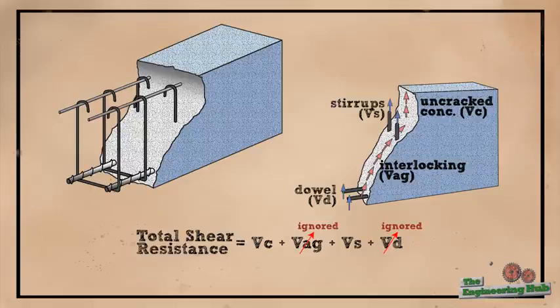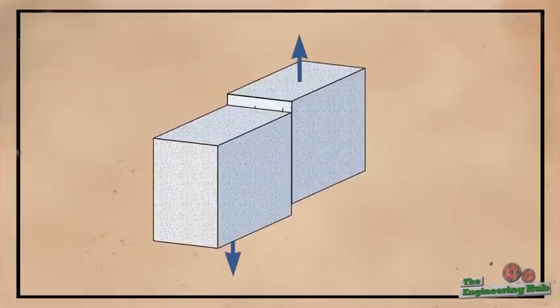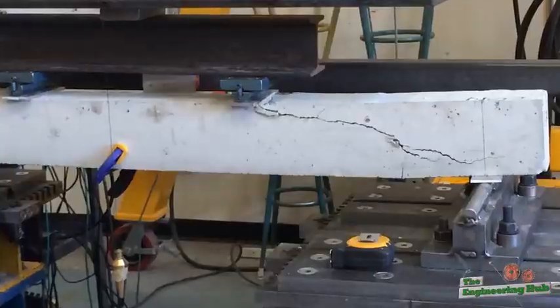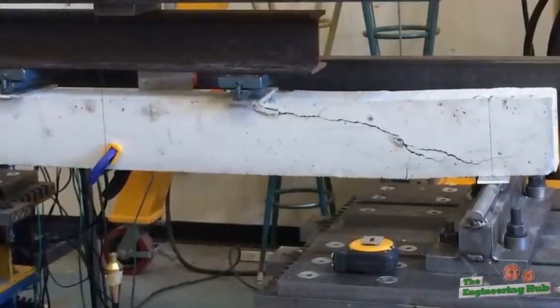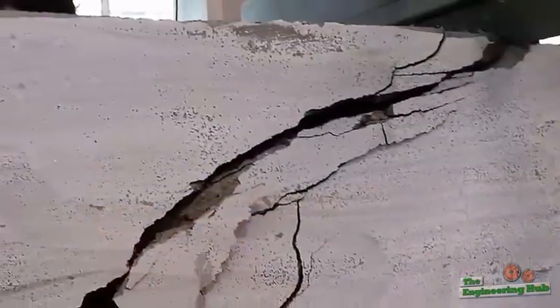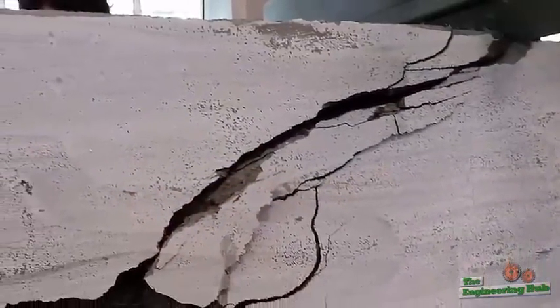Near the middle of the beam, where the shear forces are low, designers tend to increase the spacing or completely eliminate the stirrups. Earlier we saw that the shearing forces act perpendicular to the beam, and yet the crack tends to follow a curved trajectory. Why is this the case? Why doesn't a beam crack vertically down across its entire depth?